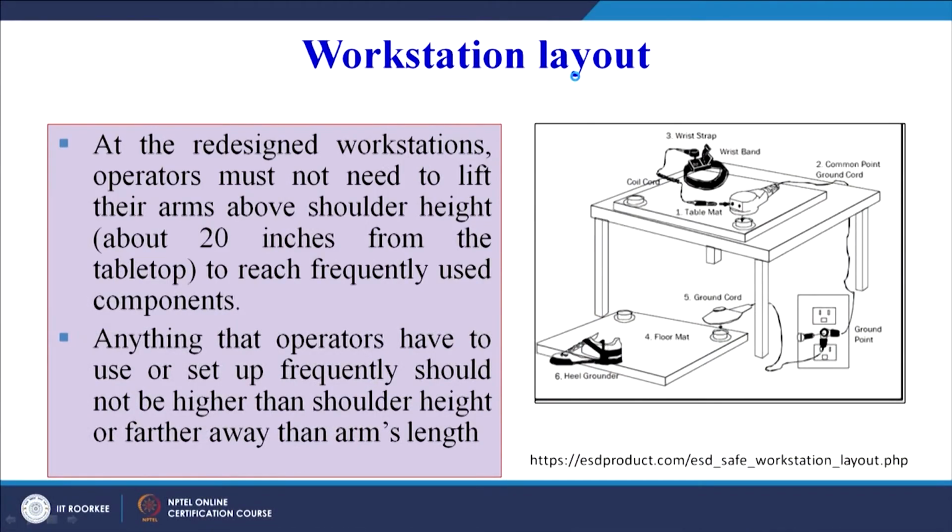So again, this example I have taken, this is also a dais that we are using. The height must be adjustable as per the height of the speaker. Similarly, the table which is being used in the assembly line, the height must be adjustable as per the comfort or as per the liking of the operator. Workstation layout. Now we can see so many different equipment the worker has to use when doing some assembly operation. In the redesigned workstations, operators must not need to lift their arms above the shoulder height.